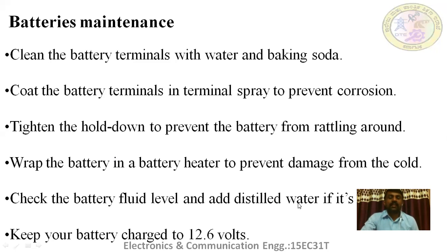Add distilled water if it is low or if it demands. So there are level indicators in the batteries, in lead acid batteries. Maintain the required level for better charging and discharging. And one more thing, this is the important thing, always maintain a charged battery at 12.6 volts.